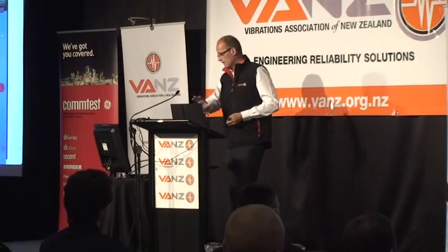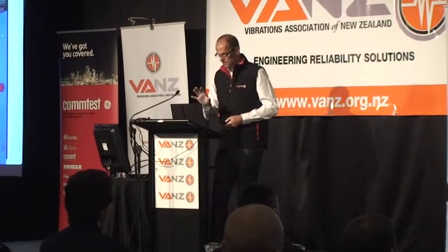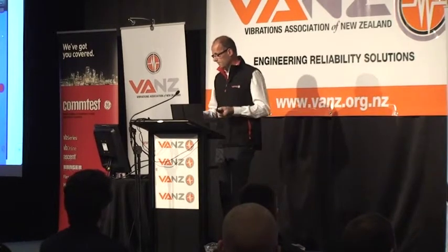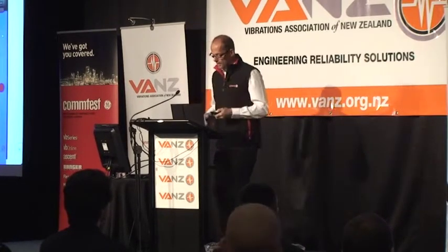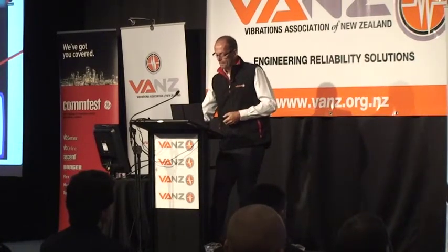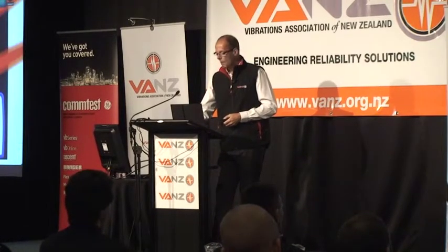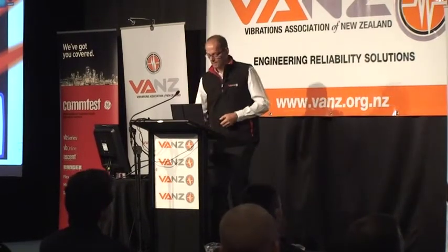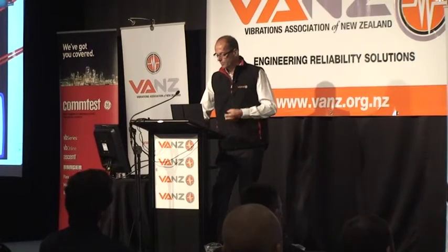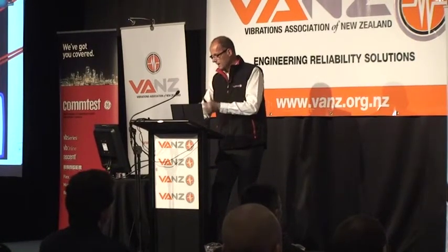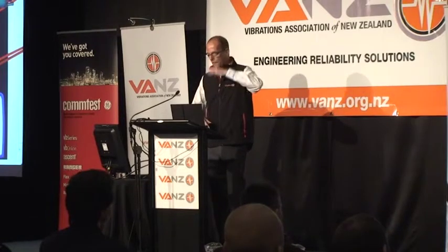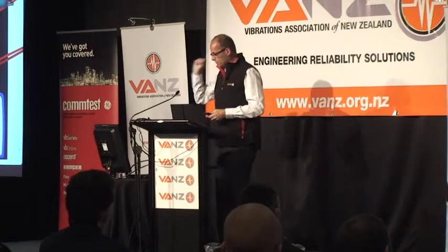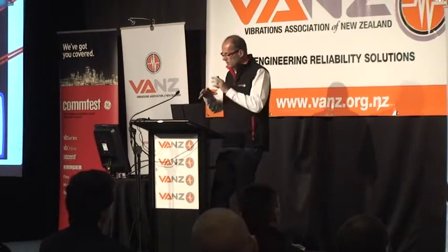There's a lot more I could tell you about how you can use strobes in this fashion, but just be aware that they are a very helpful tool. They can help you identify if something's rattling or vibrating. In this particular example, there's two belts, and one of them's flapping. So, okay, it's flapping a lot, just for the sake of this animation. If we turn on the strobe, I've got it firing at the running speed, and it happens that the belts are flapping back and forward right at the running speed. So flap, flap, flap. But because we're flashing at the running speed, we don't see the motion.